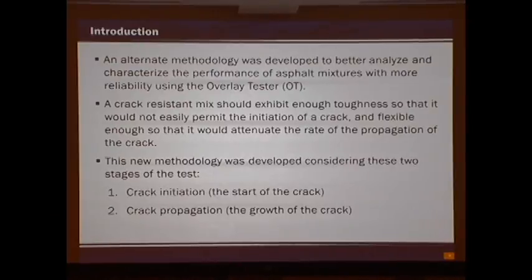So the new methodology that we came up with here, and that UTEP came up with, was really going back to some of the first work that was done on the overlay test at TTI, and was basically looking at the separation of the crack initiation, which is the start of the crack, and the crack propagation, which is the growth of the crack. Those are two different phenomena going on, and to analyze the data, we needed to separate those.